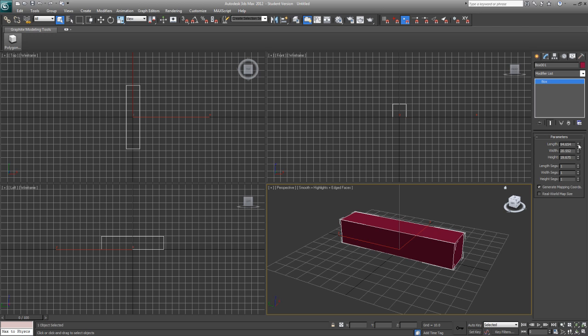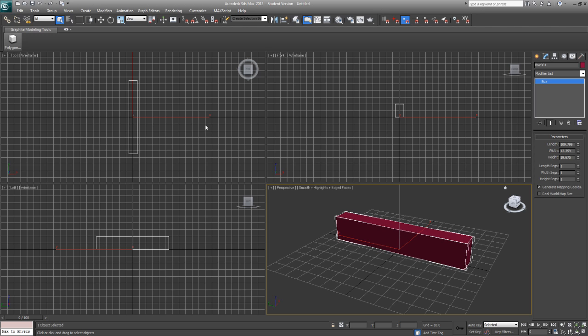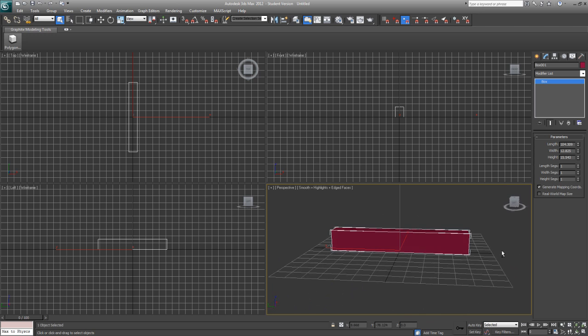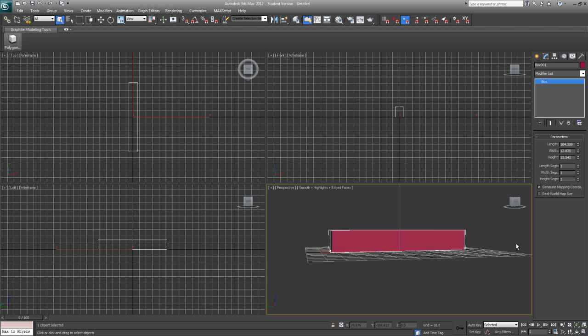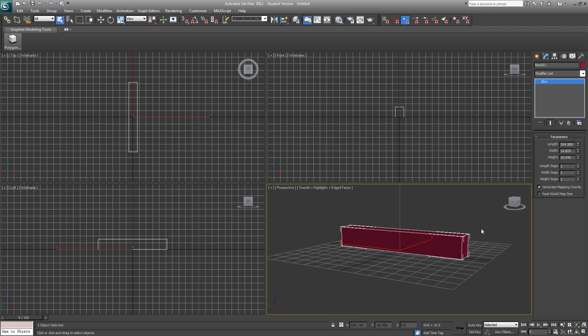So right now this box is only editable in the way that we can adjust its 3 dimensions. So from the top view, we're going to want it skinny. Most models are going to be fairly skinny. So that'd be our width. We're going to make the model fairly skinny, and the length should be whatever, and bring your height down a little bit. Okay, so that's basically the fuselage. From here we can't edit anything else, so we need to change this into something that is editable.